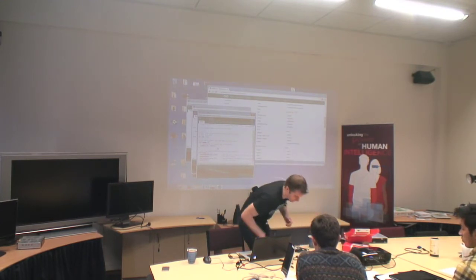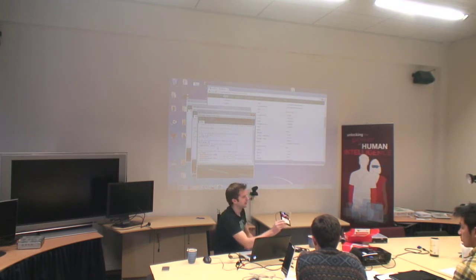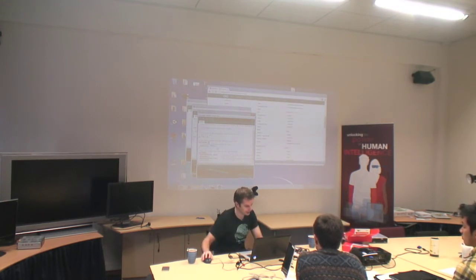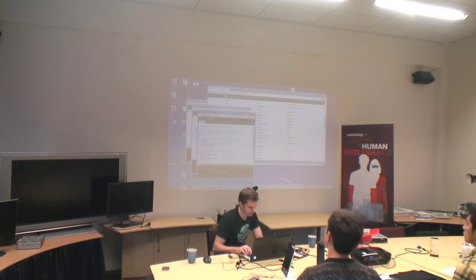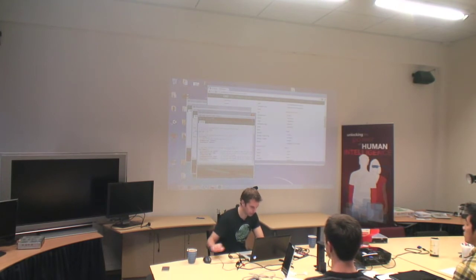Ground, and you see, I've plugged another light in, but nothing's happening because it's plugged into pin 12 now, and I haven't actually told pin 12 to do anything, so it's just going to sit there and do nothing. So let's modify our code a little bit. We actually want pin 12 to be output as well, and 12 high, whoops. 12 low, and let's cut this time down a wee bit.